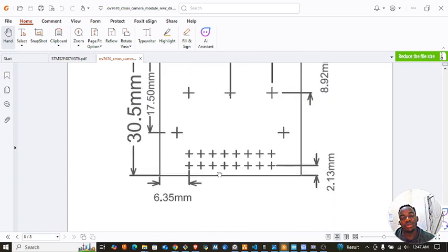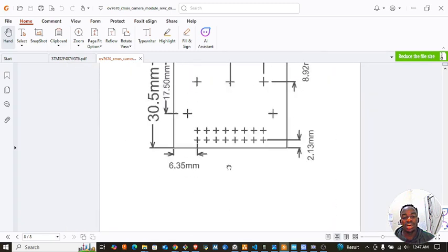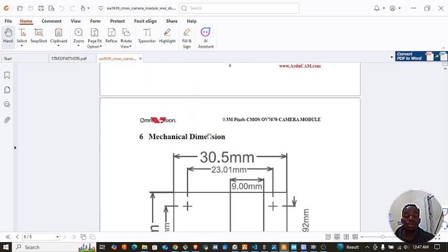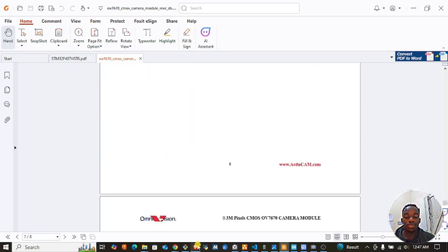And next is just a number of pin descriptions and dimensions, etc. So this will be helpful when you are designing the footprint. I've not found a footprint on EasyEDA, obviously, because this is a module. The one that is available is on SnapEDA, is it? Yeah, SnapEDA. There is none for EasyEDA for some reason. So yeah, we'll have to create one ourselves.